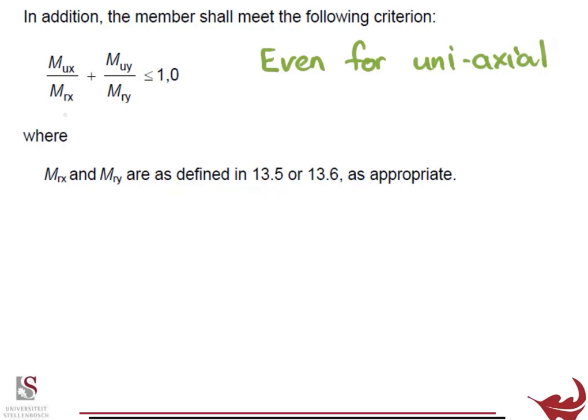So this protects you from the time where you've got a low axial force, and you end up designing it as a beam, so you don't account for the beneficial interactions of beam and column and effective lengths and all those sorts of things. So you're just checking that moment over moment of resistance is okay, and then you add in the moment about the other axis as well. You'll see there's no compression term. So this really comes into play when axial loads are low.